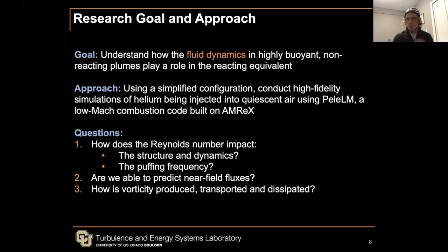Fluxes are extremely important in theoretical modeling of buoyant plumes, jets and plumes. And so we want to be able to predict properties of the flow in the near field. We already know how to do it in the far field. We want to do it in the near field. And then lastly, we want to look at how vorticity is produced, transported, and dissipated. And as you'll see, vortex dynamics play a huge role in these flows. And obviously we don't have enough time to actually address these questions fully, but I'm just going to highlight some of the things, particularly that we're using with yt and how it makes our lives so much easier.